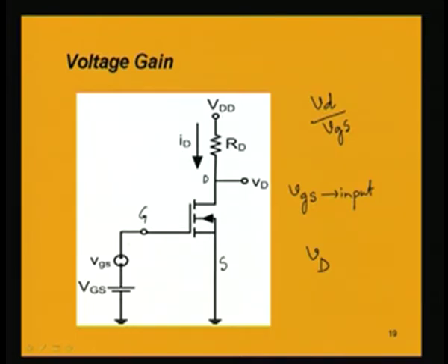These two voltages are there to make the gate to source voltage positive. That means the gate is kept at a voltage positive with respect to the source. Similarly, the drain is kept at a voltage positive with respect to the source. These two conditions must be met in order to make the MOSFET on or make it conduct.